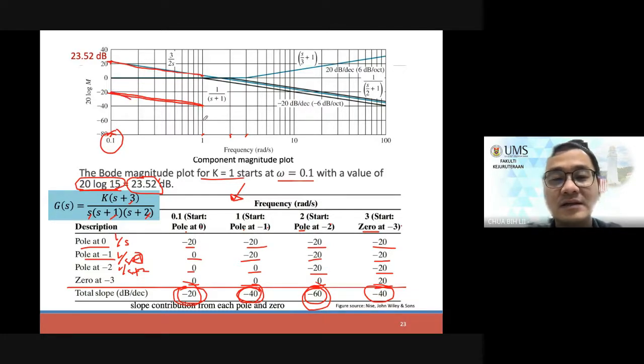Then for this minus 40, you just use this point to minus 40. Again, adjust your ruler in this way. Put it in this way at this point, now push your ruler up so that the ruler is parallel to this line. So draw until point A. Then for this minus 60, again, your ruler all the way like this. Then push it from this point, you draw the line.